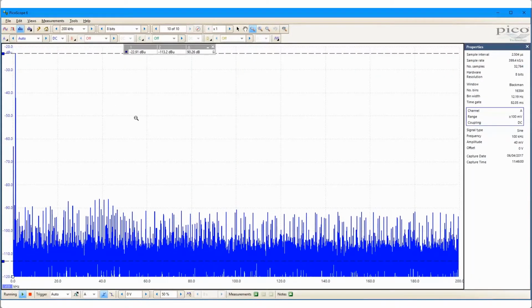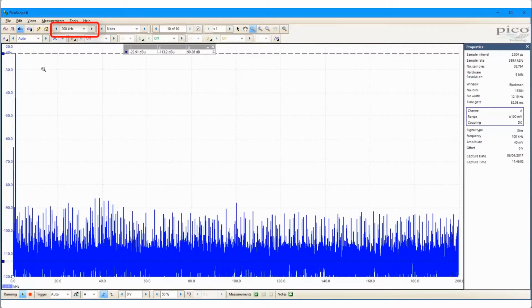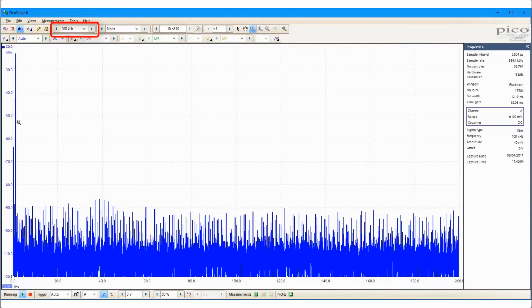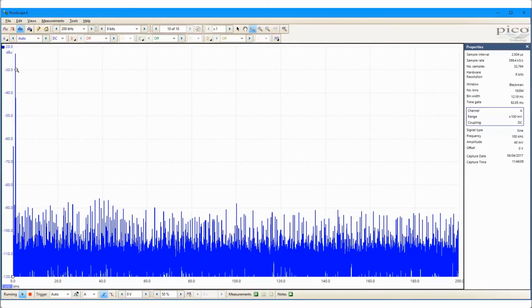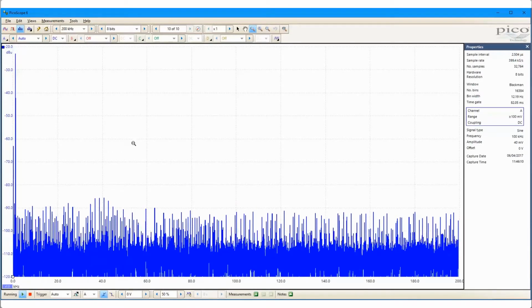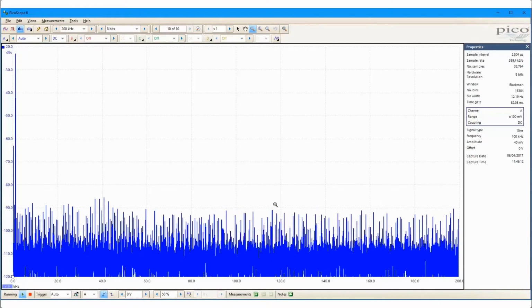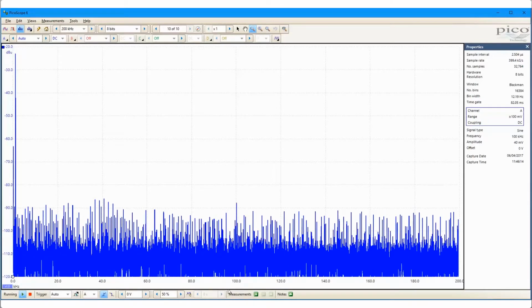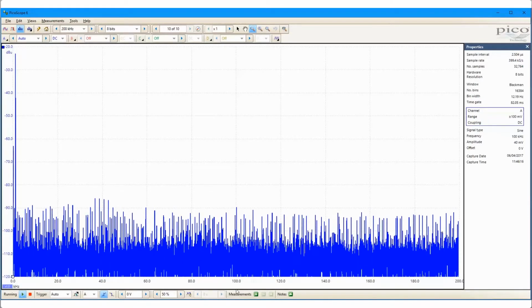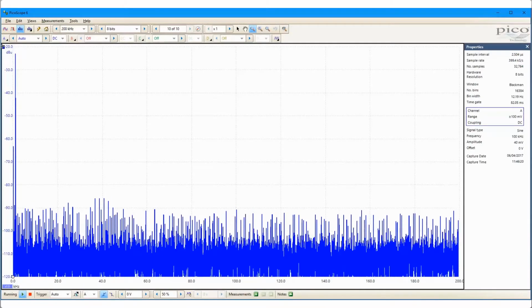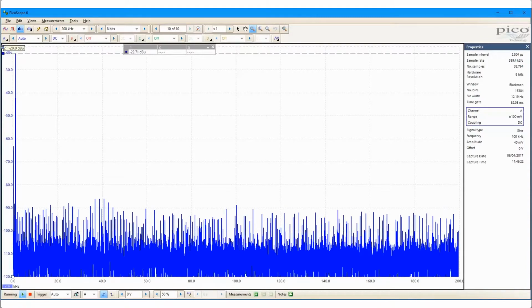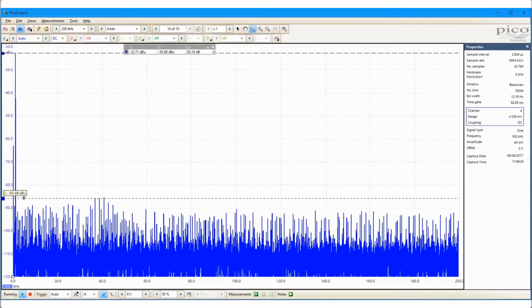The spectrum range is set to 200 kHz, and here we see the 1 kHz sine wave very clearly. But the 100 kHz interference is lost amongst the harmonics, and that is typical of FFT with an 8-bit scope. A quick measure using the rulers shows a spurious free dynamic range of about 63 dB, which is also confirmed using the automatic measurements.